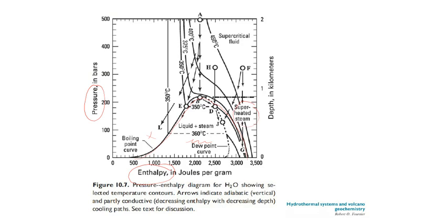Above the critical point at 220 bars and 350 degrees for pure water, we find a supercritical fluid region. The fluid rising towards the surface can take several paths depending on where it starts, for example in the supercritical dry vapor zone, and where it ends, as in the saturated liquid zone. High enthalpy steam, which is decompressed adiabatically, will follow a vertical line and exit in the form of superheated steam.